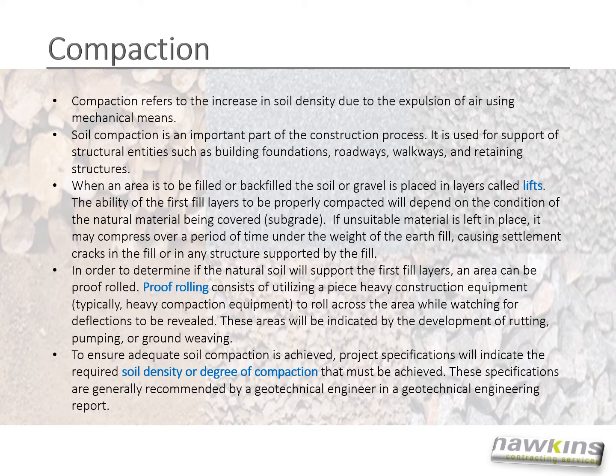To ensure adequate soil compaction is achieved, project specifications will indicate the required soil density or degree of compaction that must be achieved. These specifications are generally recommended by a geotechnical engineer in a geotechnical engineering report.